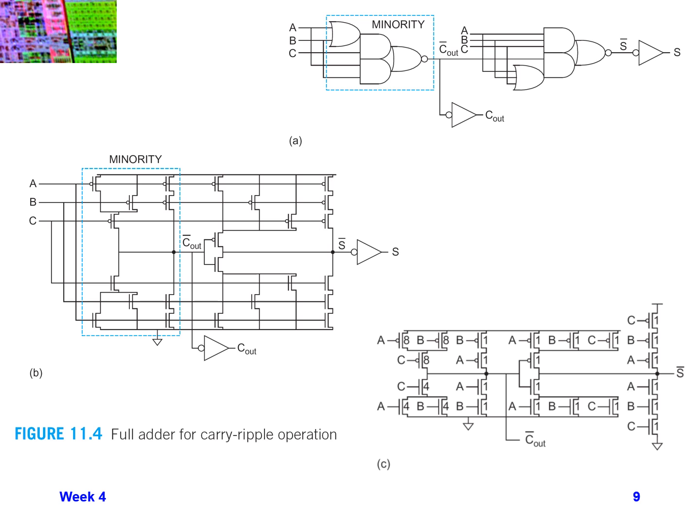One thing that you can see here that's critical is the very input where C is coming in on the very left hand side. You can see that's sized 8 and 4, whereas pretty much all the rest of the sizing of the cell is size 1. The reason for this is because, like I said, the carry in to carry out is our critical path, so we want that to be as fast as possible.